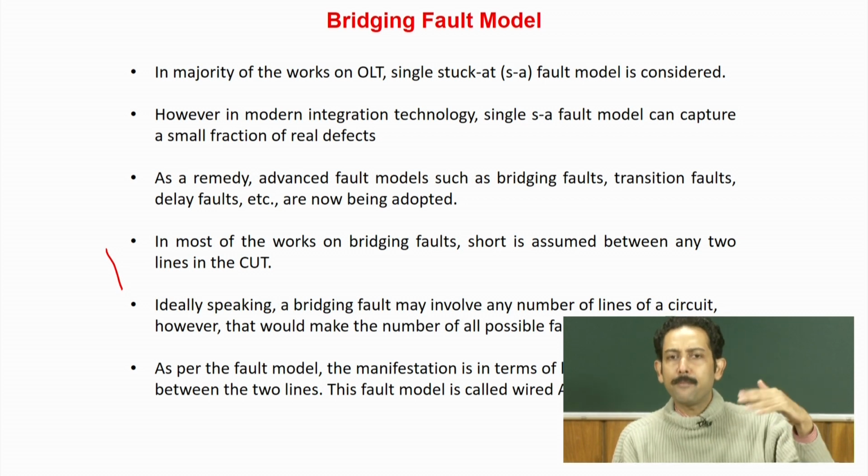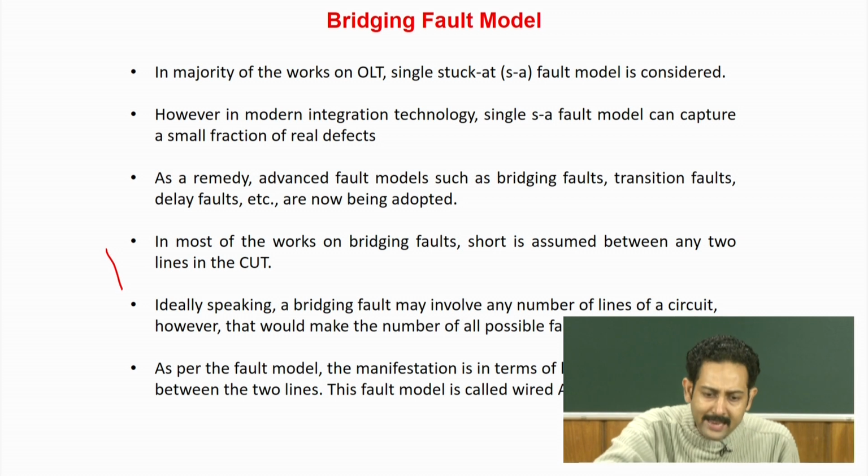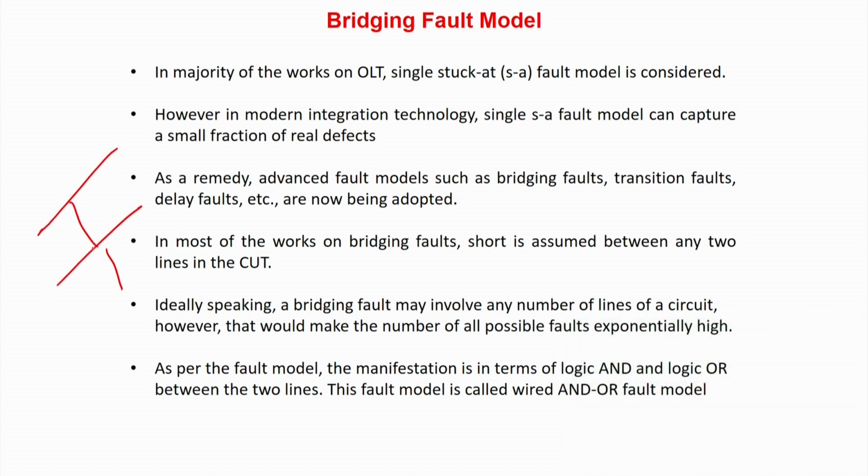The higher the micron technology, the more is the gap between the two lines laid out in the VLSI circuit. As the gap between the two lines is high, the probability of faults occurring there is lower, or even if faults were there, they generally led to lines being cut, that is a stuck-at 0, or sometimes something happened due to interference, etc.